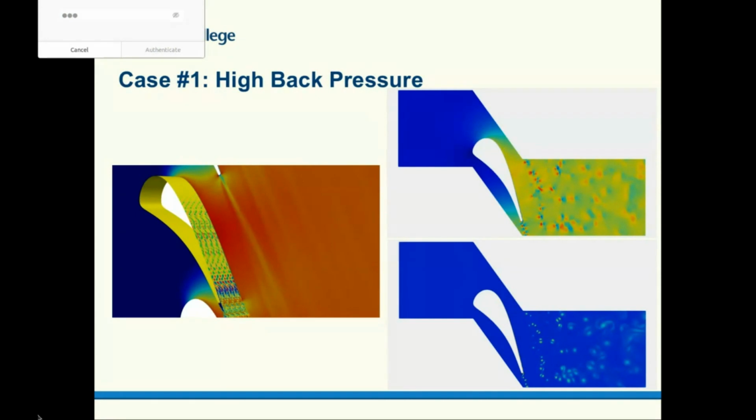So the clean inflow, if you look at the left-hand side image, which is 2D, it's only in the X direction, from the left to the right of the page, hits the blade, then goes around the suction side, which is the curved part here where my mouse is. Hopefully you can see that. And then because of the curvature, instabilities start to occur, and you have turbulent transition, so it goes into fully 3D, and you have vortices appearing that then get convected downstream, as you saw on the right-hand side images, right? So you have these very pretty